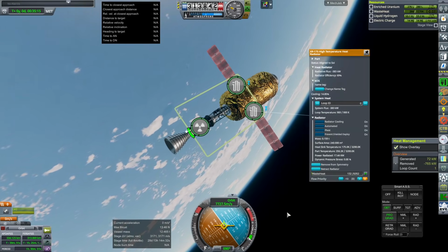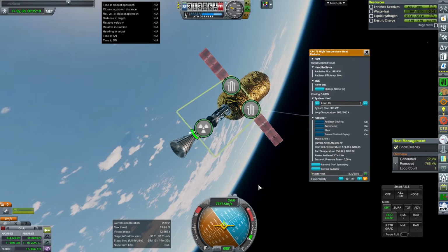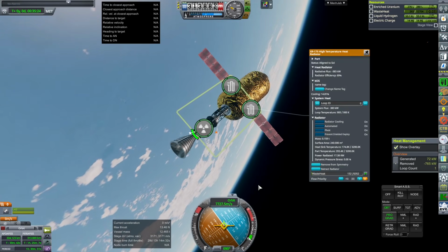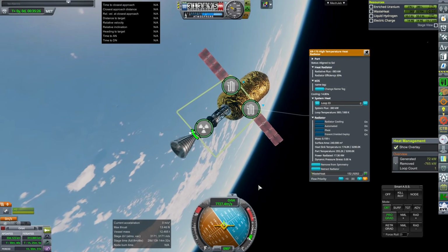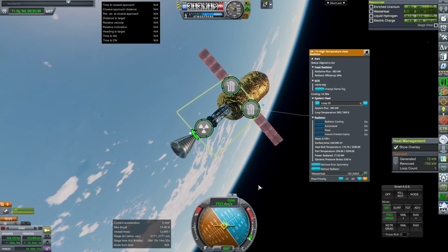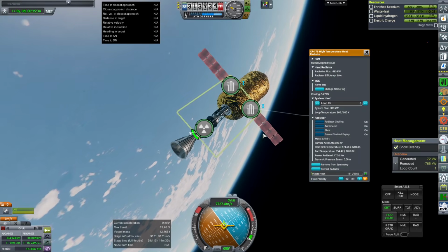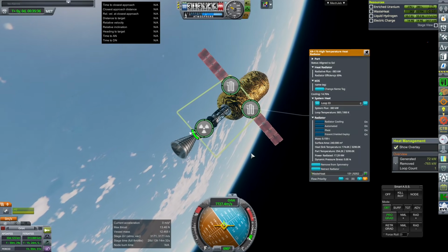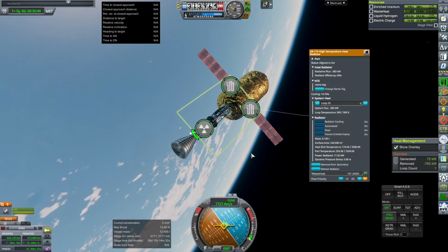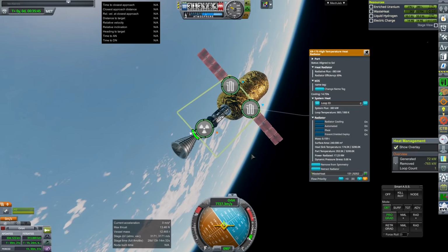So the fact that these are high temperature and have a very high operating temperature means that they are very efficient. If you've seen other radiator arrays, they might have a lot more area to deal with the same amount of heat, but that's all depending on what kind of operating temperature they have. Like titanium radiators generally operate at about 500 Kelvin, so not very hot actually. Anyway, so that's the idea,